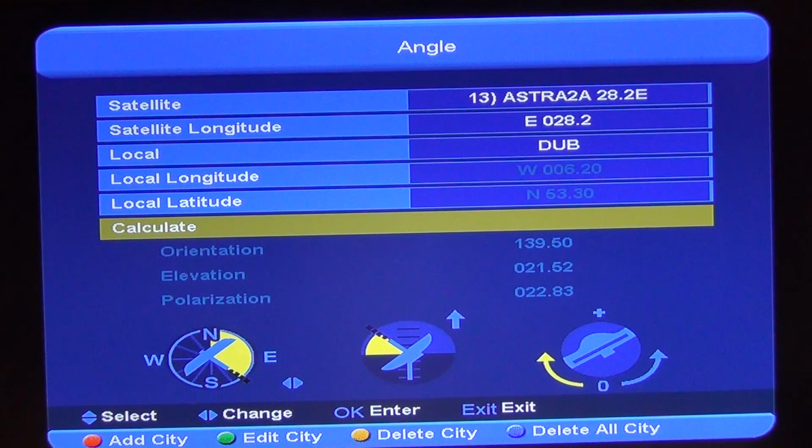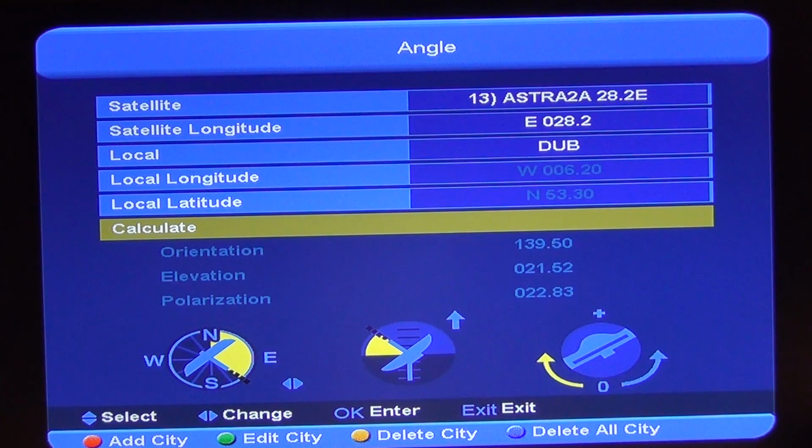But this is just so super. You're out doing an installation, and it's a satellite you've never heard of. You look it up on the list, and all you need to do is come along here. Then you can align the dish, and instead of having to go inside and tune in the box and all the rest of it, you're directly onto that satellite. You do a scan for a particular transponder, and all of a sudden you've got an ideal setup. So a really, really life-saving feature, I would say. A lot of other meters don't have this, and in terms of the easy user interface, I find it absolutely fantastic.